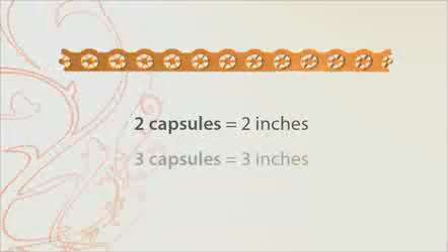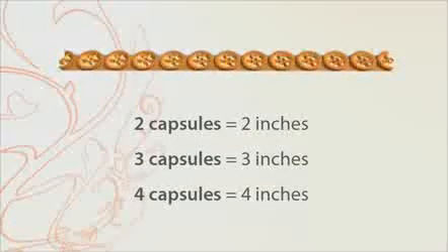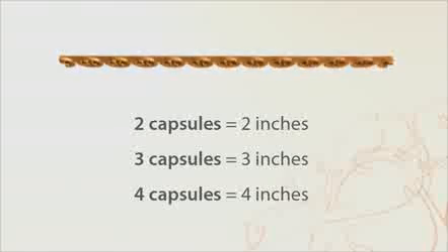The correct spacing depends on the type of installation. Refer to the installation guide to confirm the cable's output and spacing. Spacing cannot be modified during installation. This would create temperature variations on the floor.